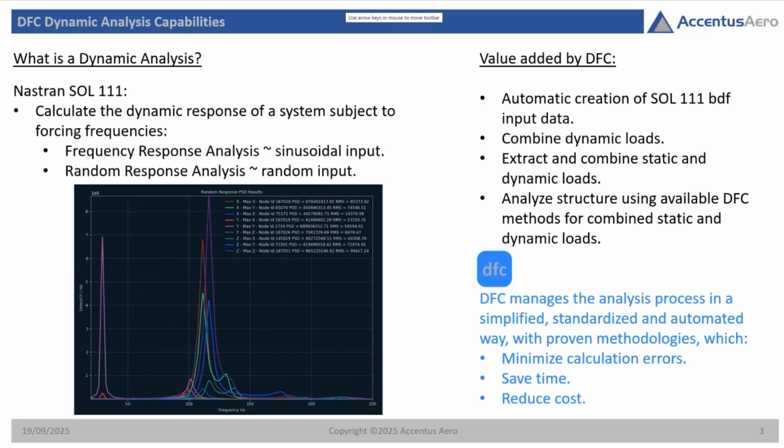And typically what you'll get from the output is a response graph, which tells you how your system is responding to your forcing frequencies, and these peaks you will typically get at the natural frequencies of your system. So there will be some amplification, and you'll get a big response there. So you are interested in looking at these peaks.